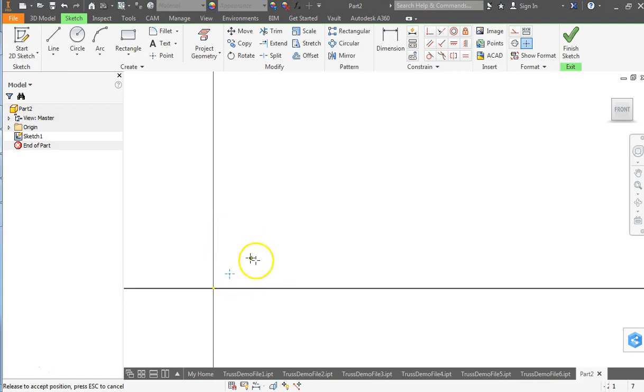And if I make a point, it's movable. And down here, Inventor tells you that 2 dimensions are needed. It sees that I've created geometry that is still free to move. I have a couple options. I can use the dimension tool and say the distance from here to the origin, a point I can reference that's already fixed, is set. And if I do that, it can't slide horizontally, and you see now that it says 1 dimension needed.